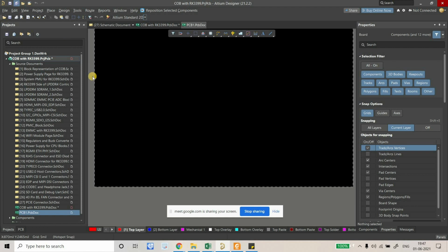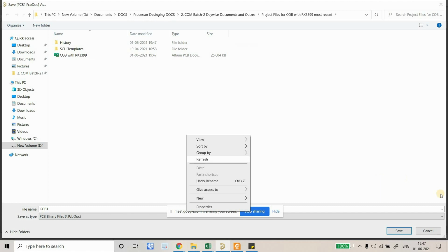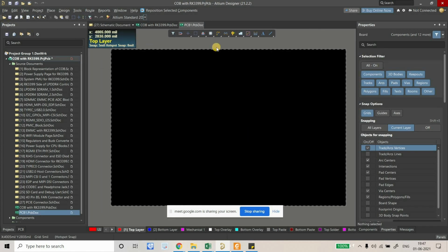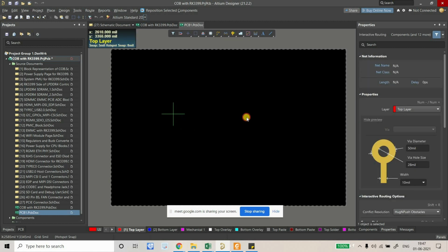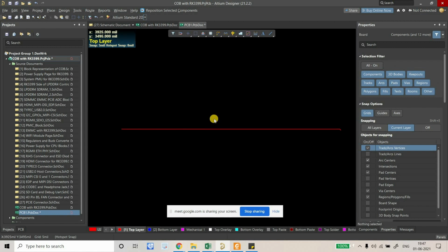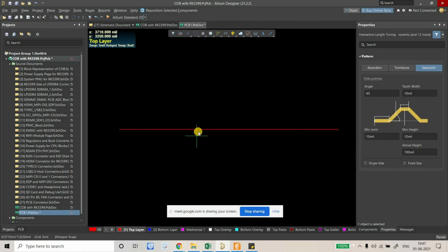All right. Has anybody already done length matching for some high-speed tracks before? Like when we're working on some modules, it may be required to length match. Okay, let's do that quickly. I'm just going to route a simple normal connection. This is just a simple route. Let's suppose I have to length match this. For length matching, we use this tab, and here we have two options, single-ended and differential, right? Let's suppose I've selected single-ended for now.